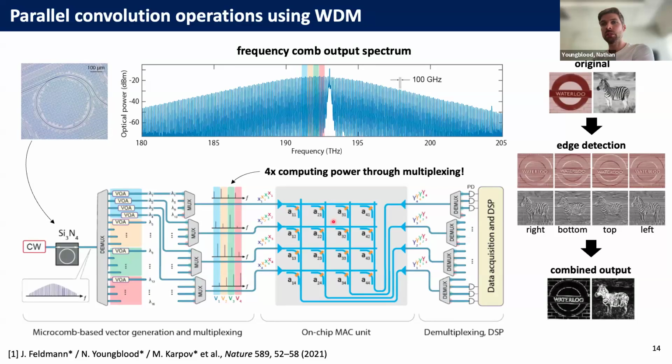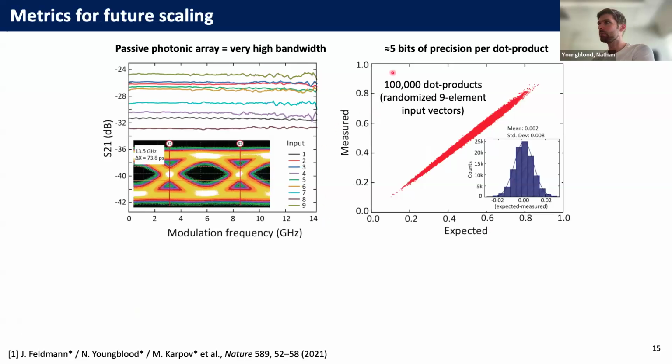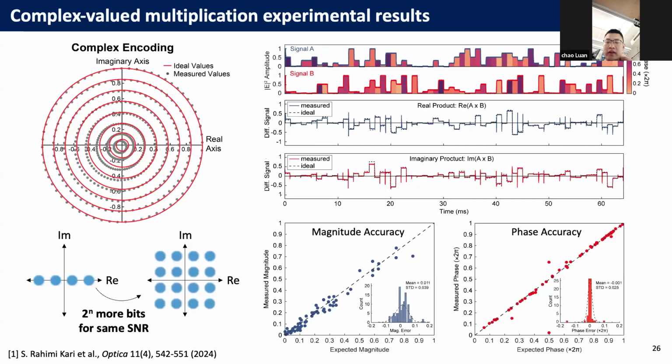We had 9 optical inputs, and each goes to one column. In this case, you program and set the weights, and those are fixed, and then you modulate the optical input. So this is really measuring the precision of the optical input once you've accurately set the weights of your memory array. And for the complex multiplication, is it also both multiplication and accumulation?